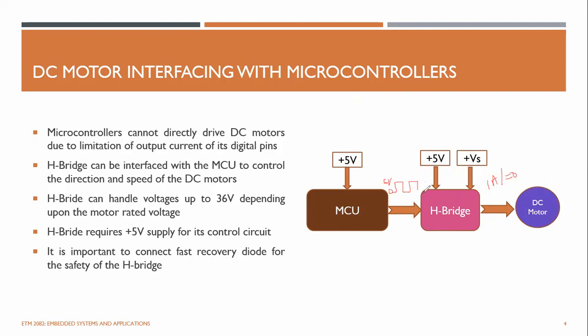And generating a high current output to drive the motor, typically 1 amp, right? This signal can be only 40 milliamps, but this can be generated as a 1 amp. So it is like an amplifier, right? Obtaining a voltage signal and generating a voltage signal which can drive a large current.